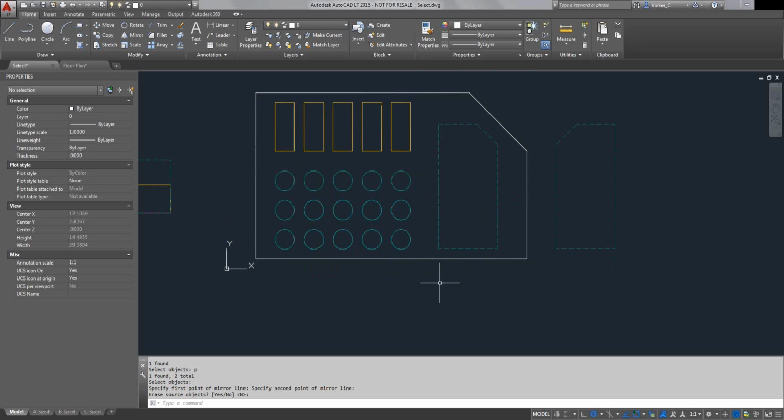It's something you've got to play with and be familiar with, but I've used it quite often as well, and these examples are going to be simplistic, obviously. It is the @ symbol, or last reference point function in AutoCAD, to select the last point I picked. For this example here, I just thought I'd show it this way.